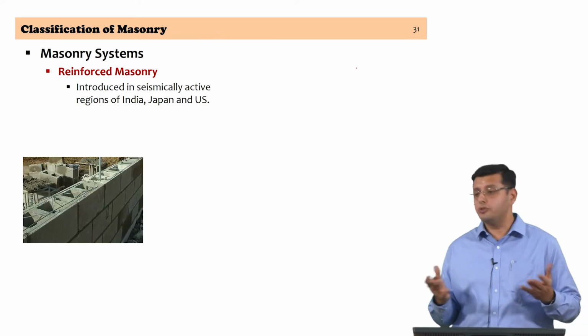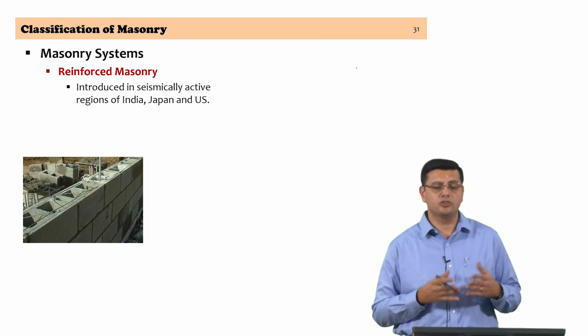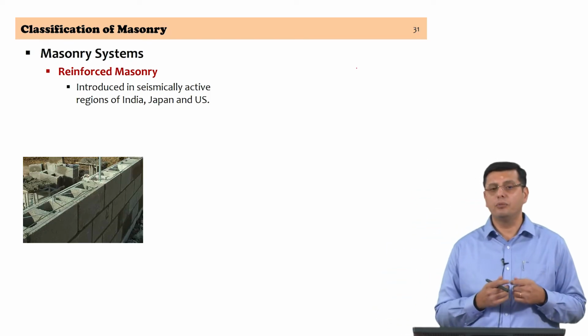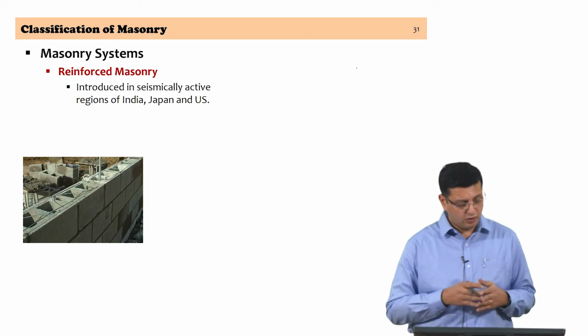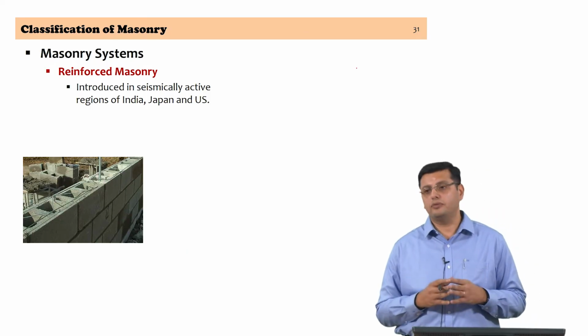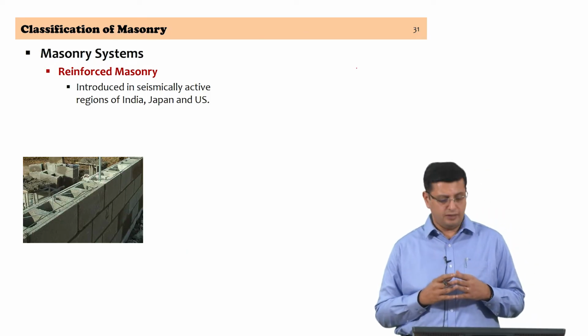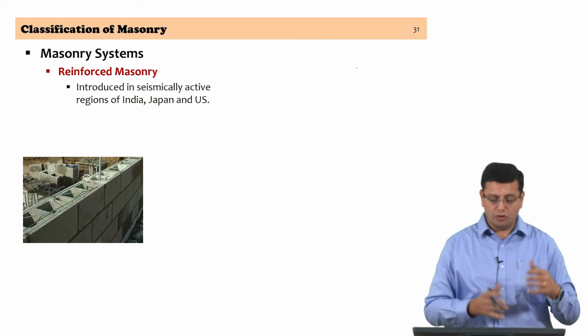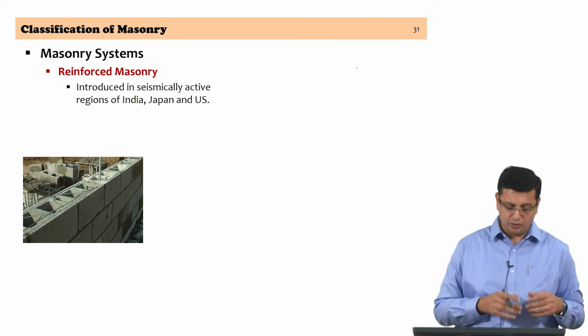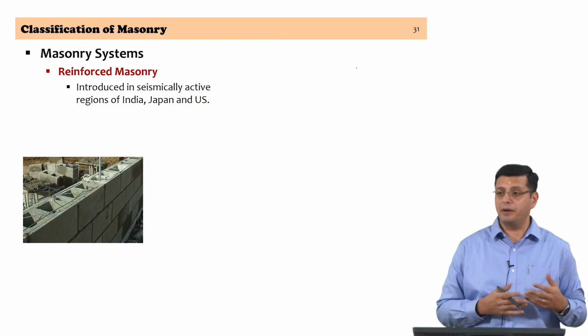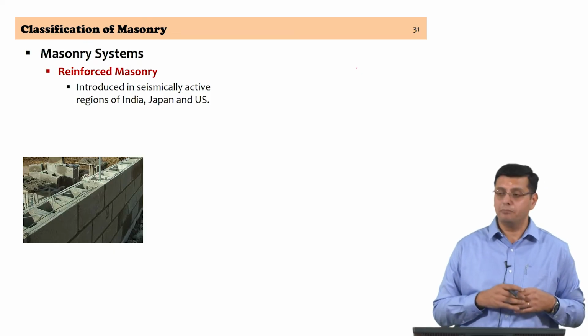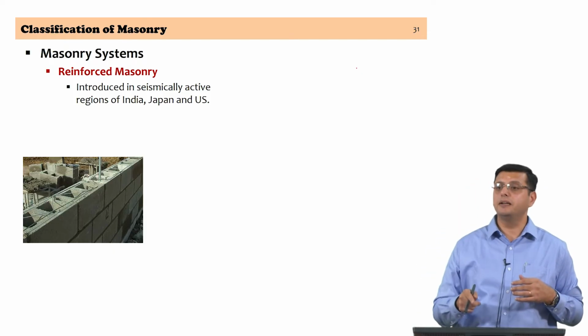So, you need to reinforce the masonry, and so there is a certain difficulty if you are going to be working with solid blocks. So, the use of hollow block construction is conducive to the need to reinforce masonry. You basically have to be placing reinforcement in pockets, and you need vertical continuity.